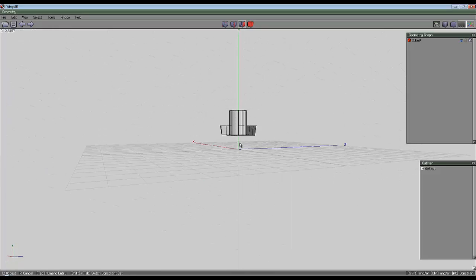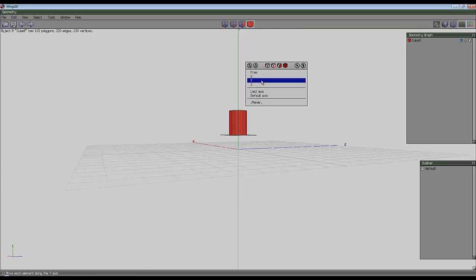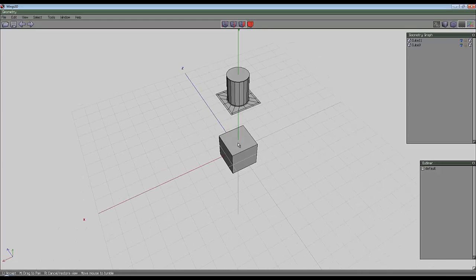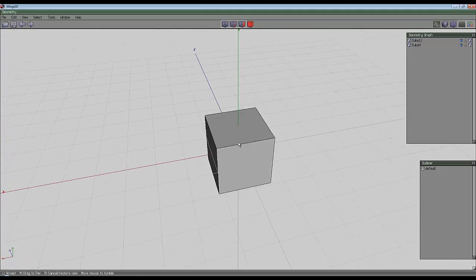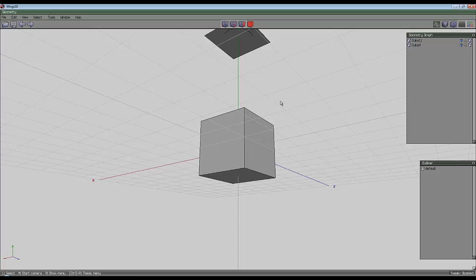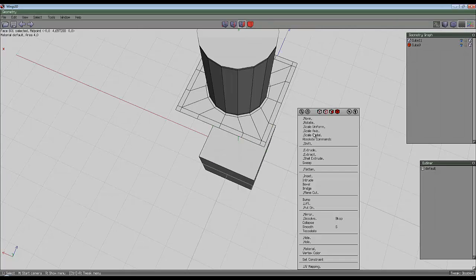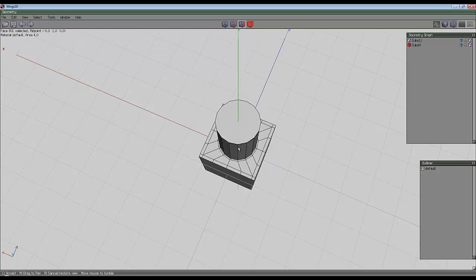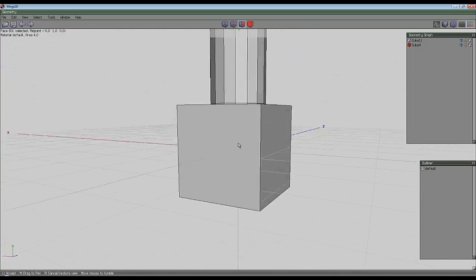And then I just select the entire thing and move it up out of the way temporarily and create another cube. Now this cube face will match that cube face in dimension at least. So I'll just show you this. If I select this face here and right click and left click on put on, and then left click on that and then right click to execute, it has put that on that face.